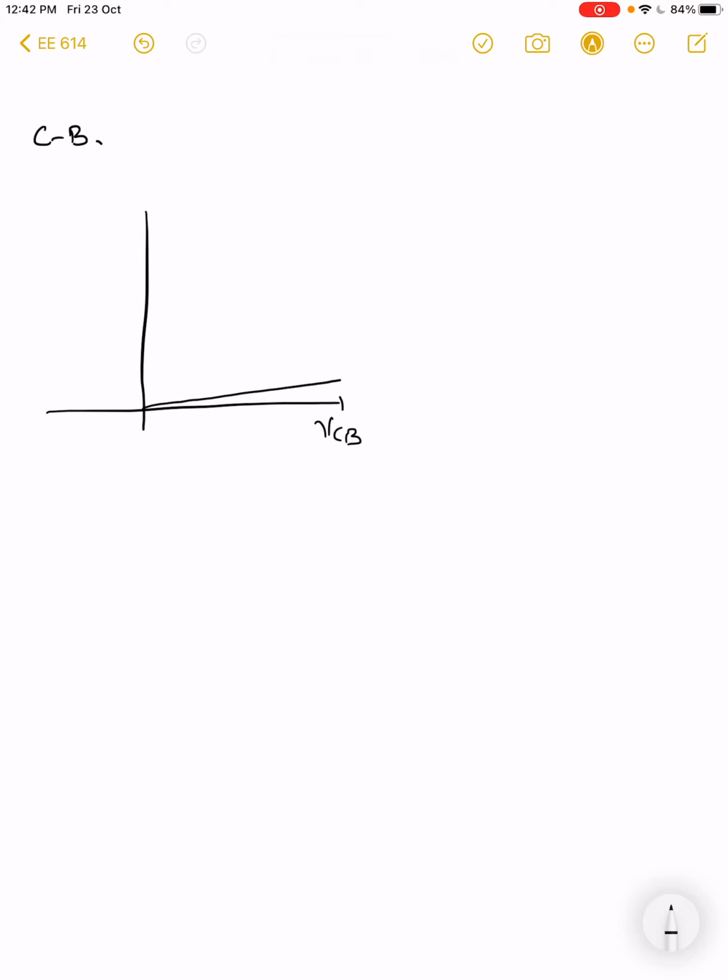And then if you increase it further, then you have a breakdown, which we saw previously can come from many means, right? And we saw that the collector current follows mostly the emitter current, because under most situations the base transport factor is almost equal to 1, right? And this is increasing emitter current characteristics. The very moment that you change the base potential higher than the collector potential, in the sense that you have a VCB which is negative, we saw that immediately the current starts dropping, right?